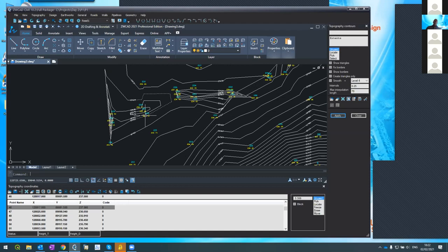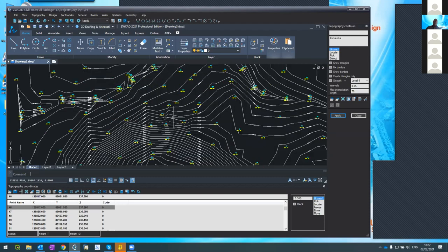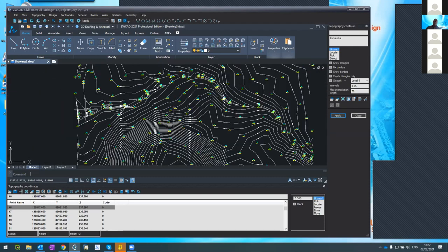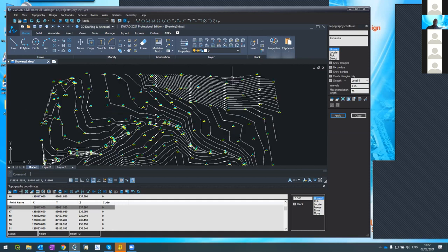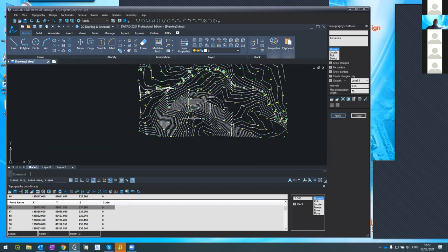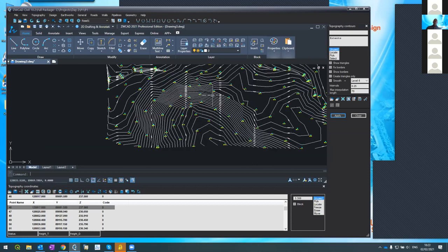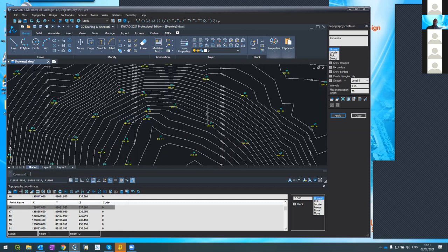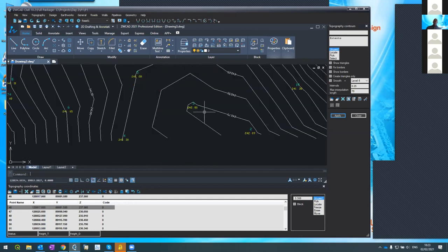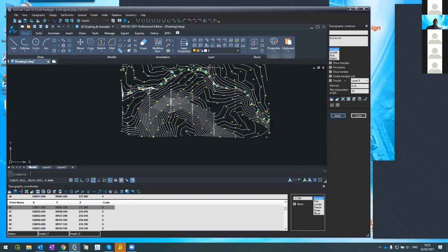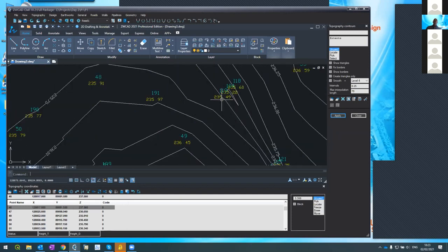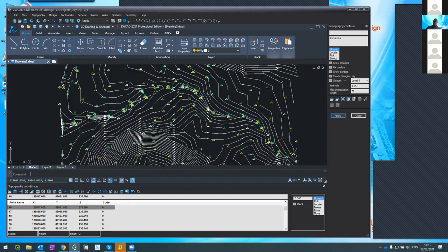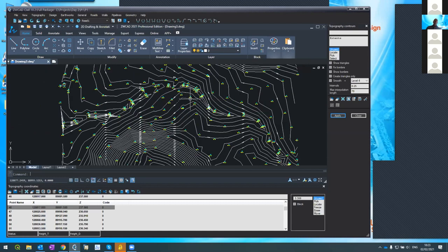Here it is. This is the project. These are the contour lines. So what we see is that there is a small stream going here. There's a small hill here, a small hill here. It looks very impressive, but look, it's only 25 cm. So here the elevation is 242, and here in the stream it's 234, so there's only 7 meters from here to here. It's not that deep. So don't be too impressed by the amount of contour lines.